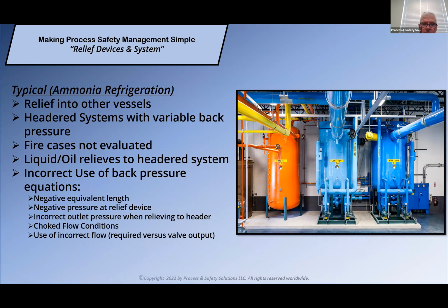So making sure you evaluate fire cases and what's going to be relieving at the same time, so that you make sure you're taking into account any back pressure situations. Liquid or oil relieves to the headered system. Well, I shouldn't have to explain the reasons why for this.